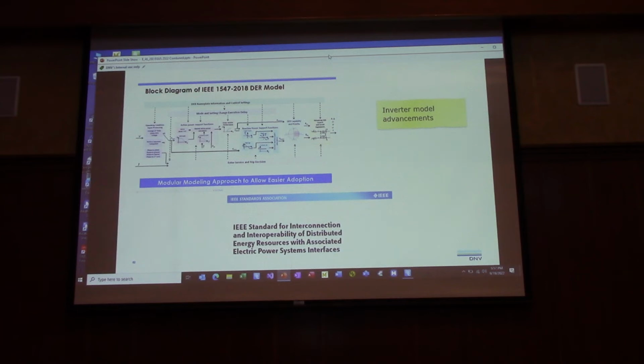So for non-engineers, that's when you have a big generator, maybe it's sitting over here, and some disturbance comes along, and maybe some switching happens, and maybe a switch is open. Well, that generator needs to deal with that and continue operating. If that switching happens over 2 seconds, that generator needs to be there when the switching is finished. So it needs to ride through the problem. And so there's all sorts of settings dealing with this that we have to be able to model in Synergi.